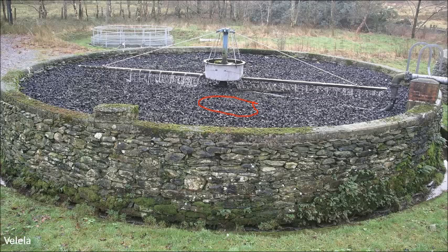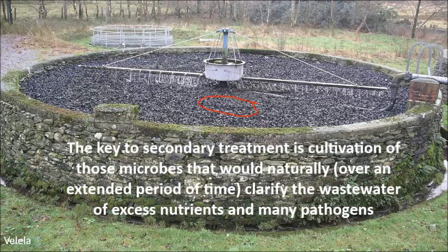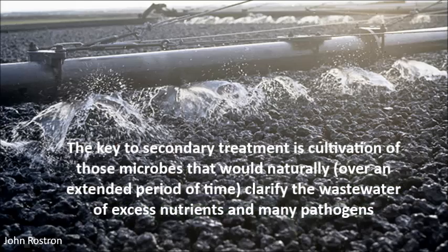But these objects are coated with a very dense community of microbes. Microbes that are naturally occurring, that would be naturally present in water supplies, although in a much lower concentration. And the primary effluent, okay, which is coming out of the primary clarifiers, is sprayed out onto the matrix. Okay, here's a better picture of what that looks like.